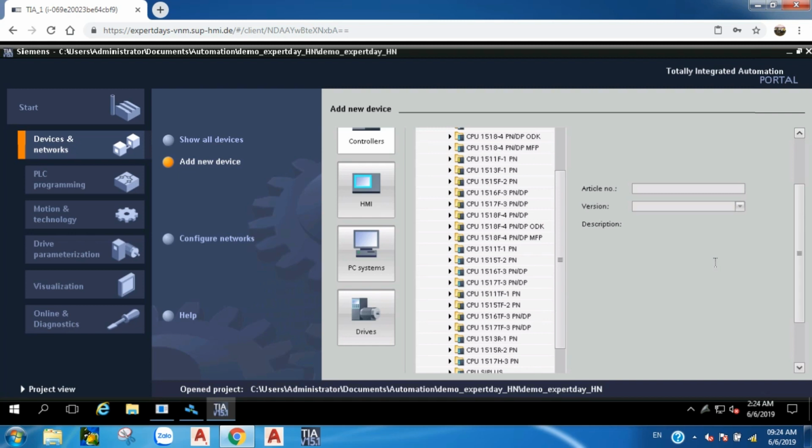For example, when we talk about parameters from the operating system, we talk about IP addresses or the host settings, OPC UA certificate handling, and if you want to see during runtime how long the panel already runs, so the operating hours. You can also access that parameter. You can also see the memory load of the panel: total memory, free memory, and the used memory. And you can see the versions of the firmware, for example, or the TIA version which is used. One thing, if you use Smart Service Monitor, you can also see how many smart clients are connected to the panel itself.